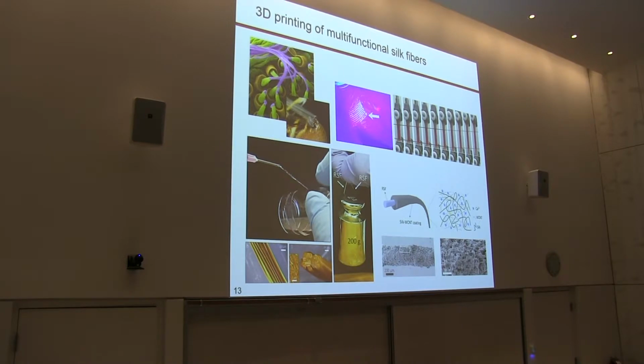For example, this kind of zigzag pattern on top of the glove, and then it can deform together with the glove. So we have a proof of concept where we put the pattern on top of pig skin, and then it can be used to measure the deformation of the skin, and also it can give the Poisson ratio by comparing the deformation in two directions.